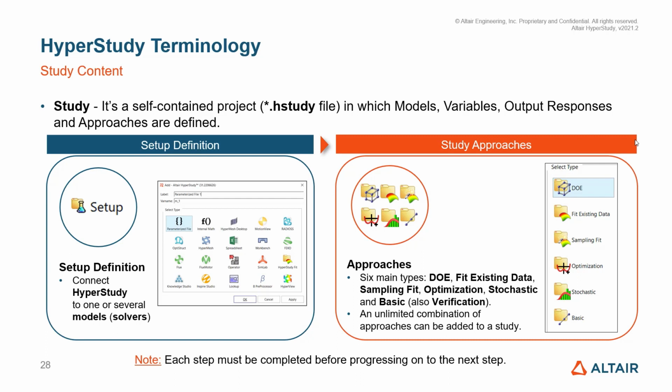So I might do 100 OptiStruct runs, and then I'm interested in 5 of them. So I can drill down to those specific runs, go look at the results contour, and it's all nicely organized in this tree structure because we're working in this HyperStudy file.